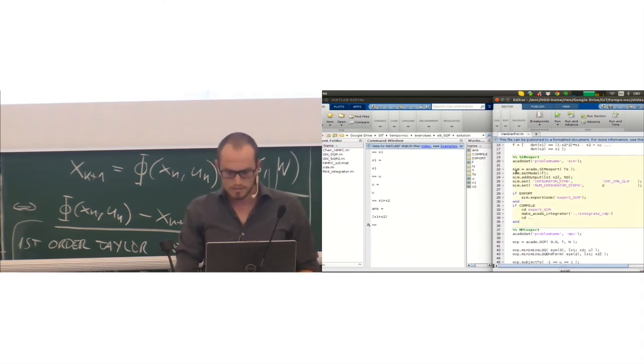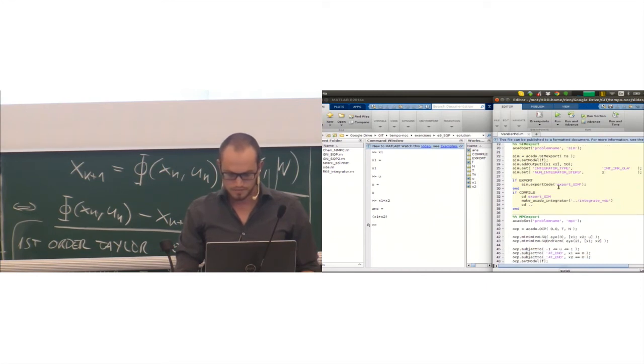In a sense, you just define the interval on which you want to simulate, so it's all fixed, and you can just use TS as your sampling time. You set the model, specify the integrator type, pass the option and specify, for example, an implicit Runge-Kutta method of 4th order with a fixed number of integration steps. Then I specify the model folder where I want to copy all files, such that afterwards in this folder you can find the make ACADO integrator.